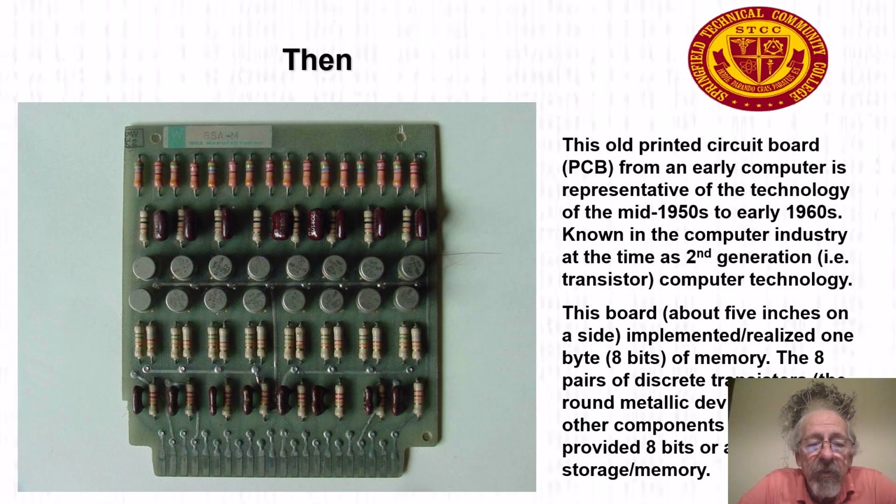Back in the day that these circuits were constructed, it turned out that to make what was called a flip-flop required 2 transistors or 2 active devices. So each pair of transistors on this is a single memory location, and there are 16 transistors or 8 memory locations, or what we call a byte of memory at this point.